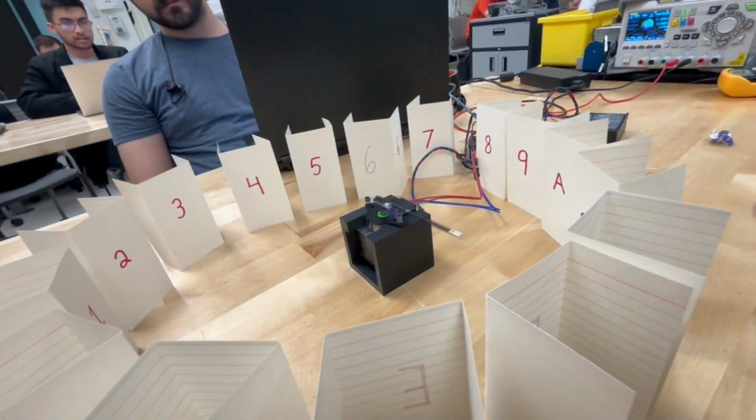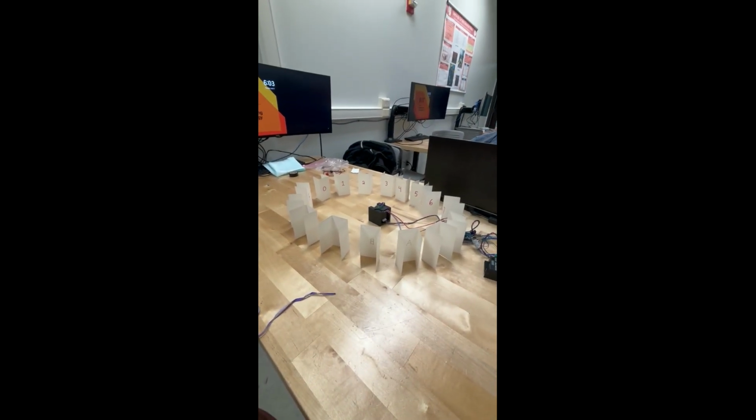4. Signal conditioning. The raw signals, like sine waves or noisy pulses, go through amplification and filtering, e.g. a low-pass filter to remove noise, and a Schmitt trigger or comparator to convert analog to clean digital square waves. Outputs: channels A and B, and sometimes Z or index.